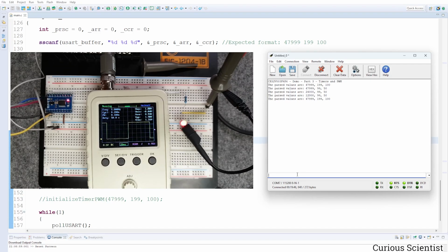That we have now a wide fat signal there. And you can see the duty cycle based on these two waves or half waves. So what I'm trying to do here is, for example, if I send this number and I say 25, and you can see that I chopped off the duty cycle. And I say 150, then I made a much larger duty cycle.